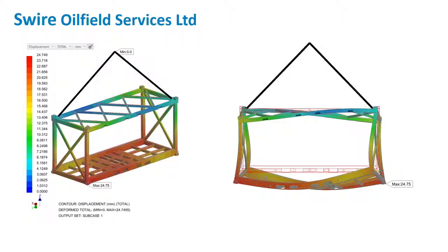So use the results, exaggerate deformations, look at the model in many different ways, and you realize how much more understanding you get from FEA than just picking up a stress level. I think it's a misuse of FEA software to just pick out a deflection value or a stress value or 10 stress values. Use it for understanding, use it to find load paths, see where the stresses are really low, etc.